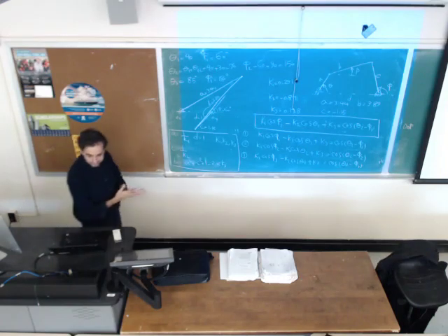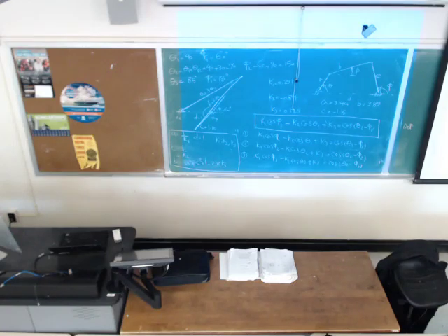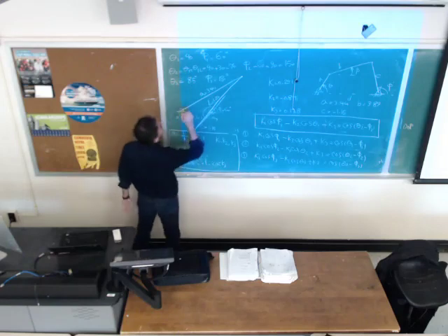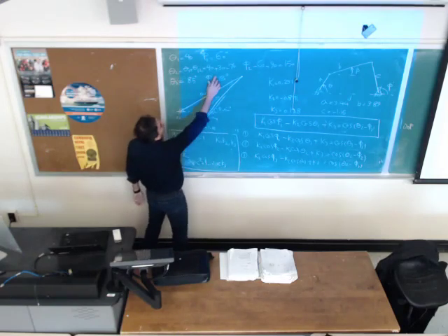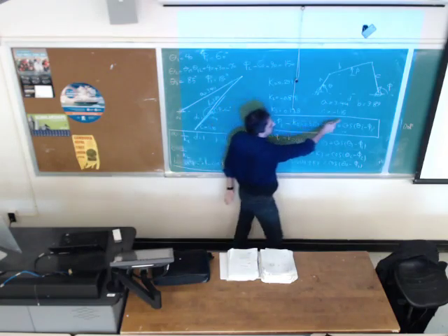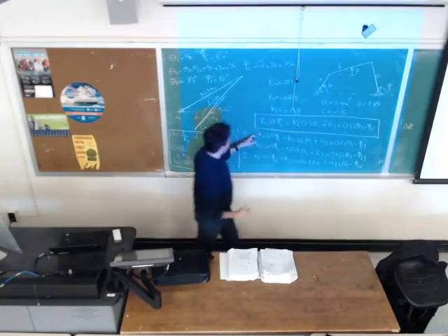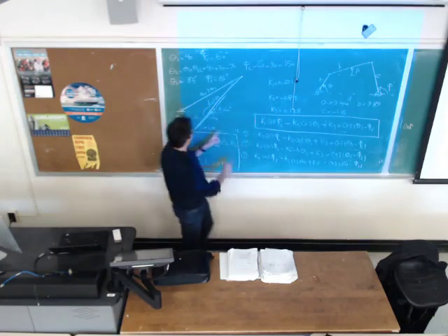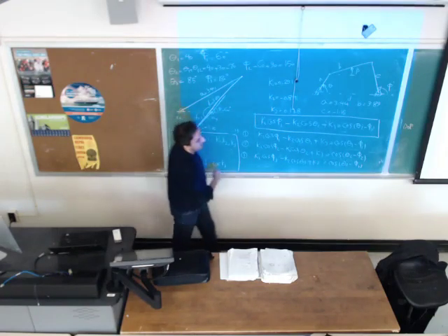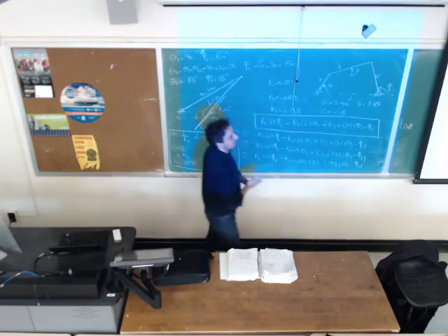So if I summarize this method, first, as a free choice, choose suitable values for theta 1 and phi 1. Then, knowing theta 1 and phi 1, find theta 2 and theta 3, because we are given theta 1,2, phi 1,2, theta 1,3 and phi 1,3. Solve for K1, K2, K3, and use these equations to find A, B, and C. And then you can sketch the mechanism in the three precision points.